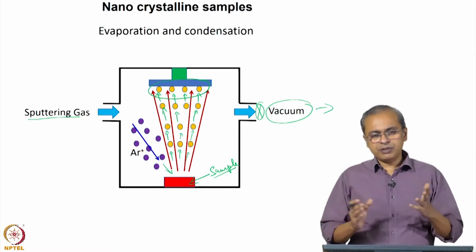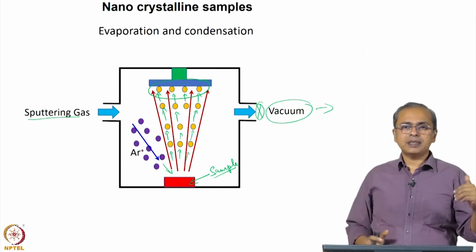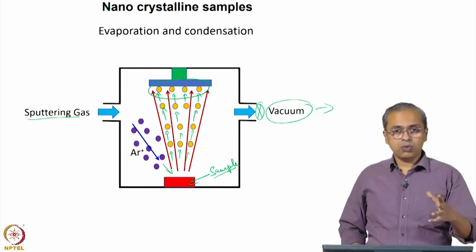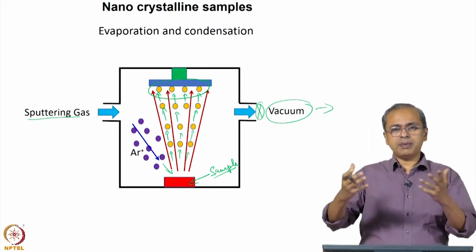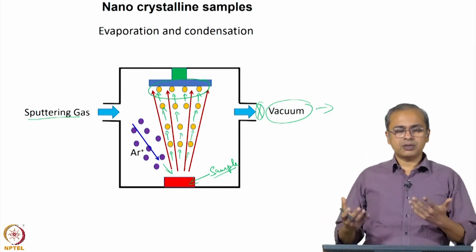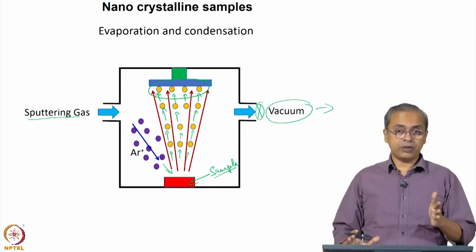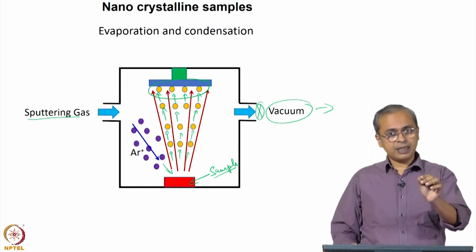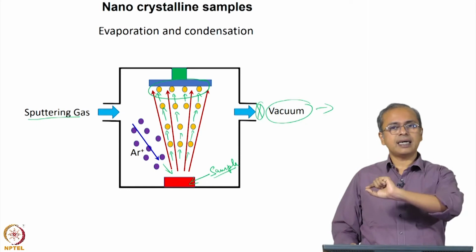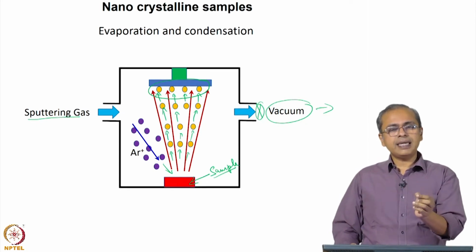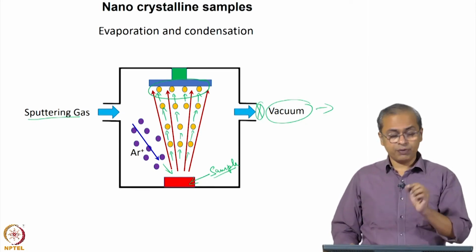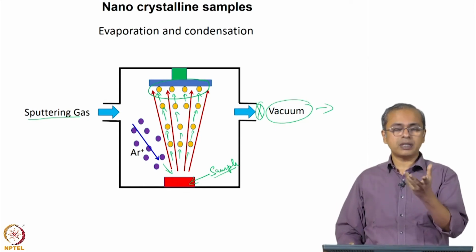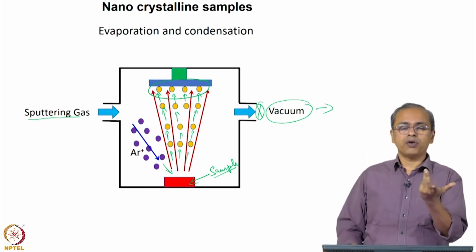In these three, if you see, relatively speaking, the thermal evaporation process is very fast. So, normally your vacuum chamber may take half an hour or 45 minutes or even an hour to reach the low vacuum that you are interested in. Once you reach that low vacuum, in the thermal evaporation process, if you start raising the current, you have to do it kind of gradually, so that you do not have non-uniform heating that is going on.